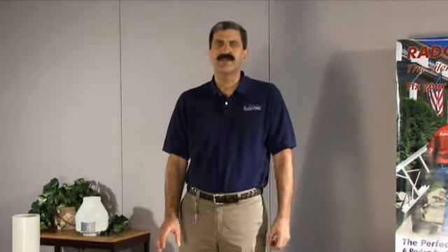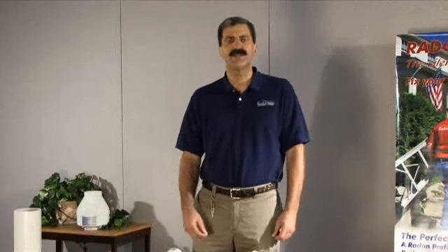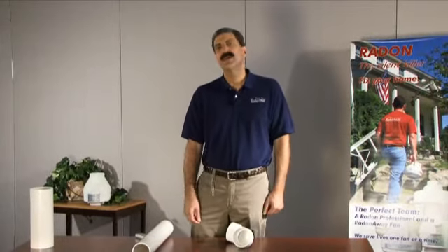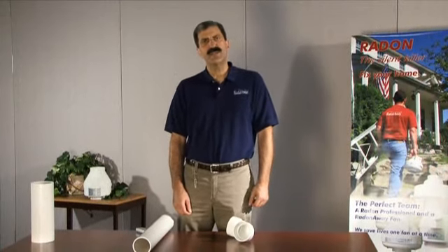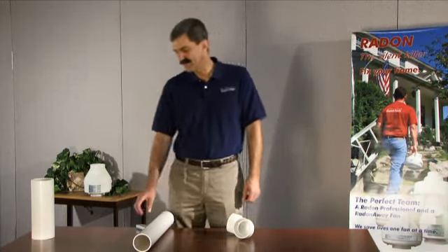So what we will do in calculating the system pressure loss is to take the bend fittings that are typically used and determine the equivalent length of those, add that together with our straight pipe, and then on the basis of that, we can then determine what the overall pressure loss is within the system.